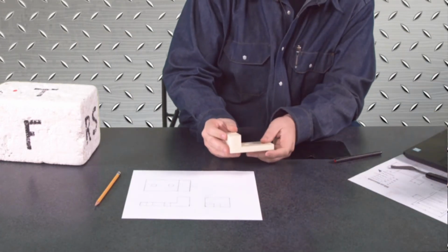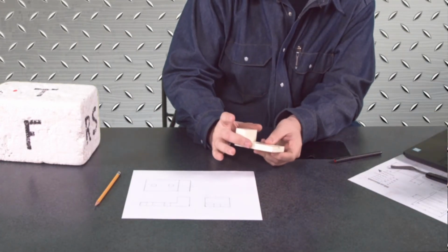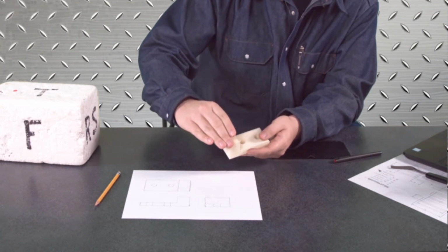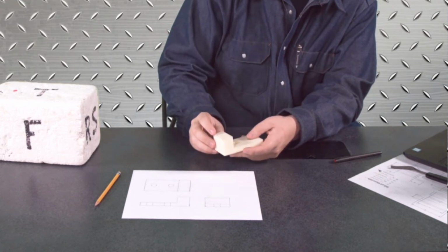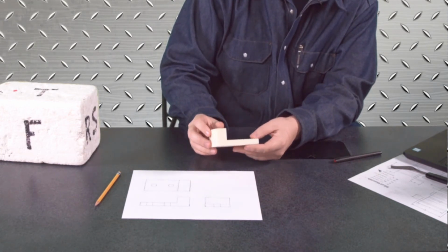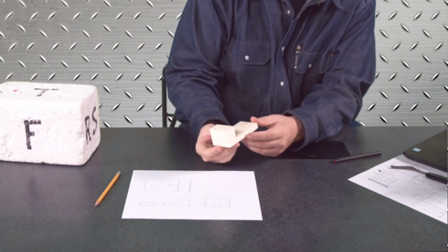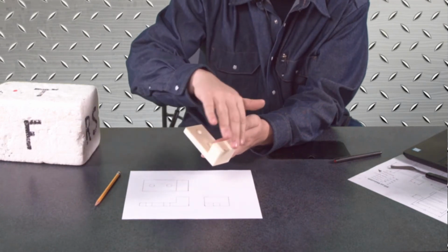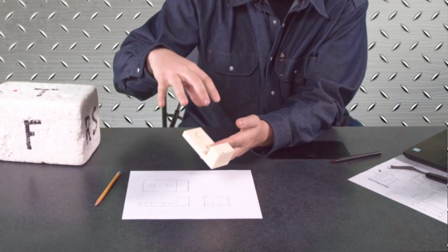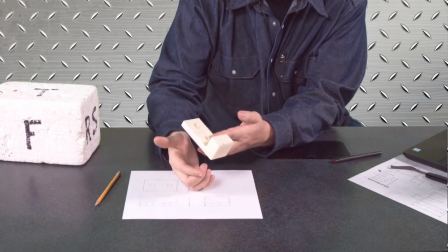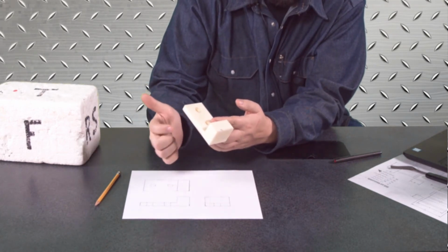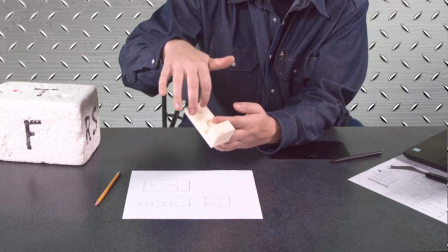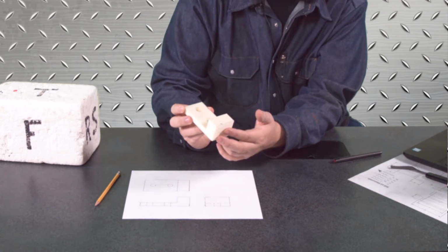Now, the only disadvantage of this is that oblique drawings kind of warp the shape. They kind of take it, and let's say this was our front side view here. It'd be off to the side, and then it just basically breaks the object and makes this at a 45 angle. Now, isometrics are a lot more preferred in my opinion because everything's held at a 30-degree angle instead of an oblique where everything's broken and it's kind of a warped shape. In an isometric, everything's based off of a 30-degree angle. So you've got your front side view, you've got your top view, which you'll be able to view with this pictorial, and the right side.